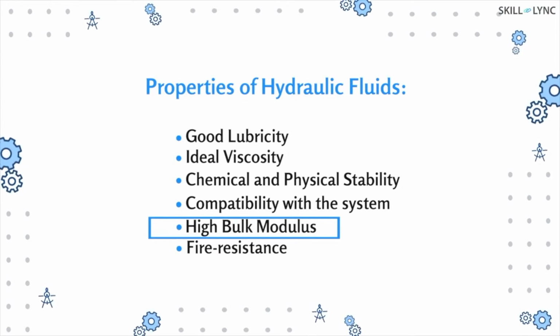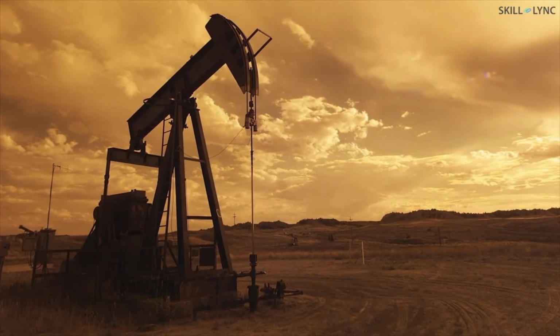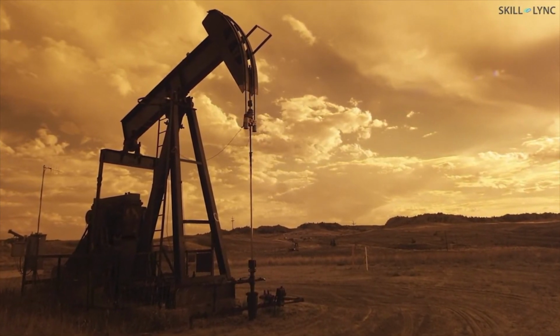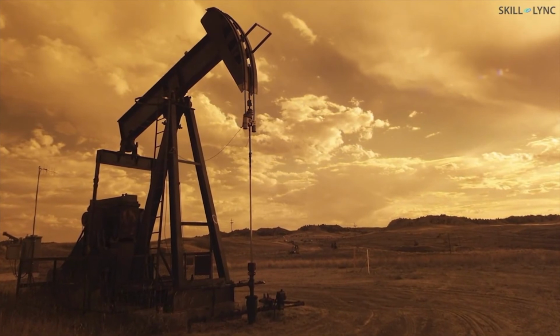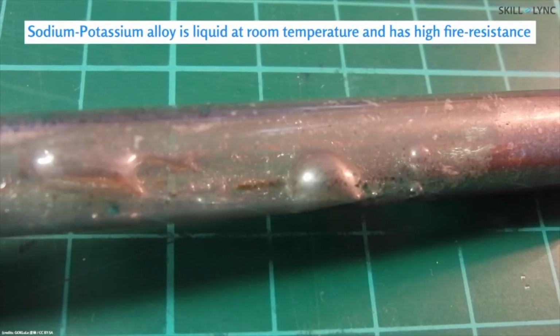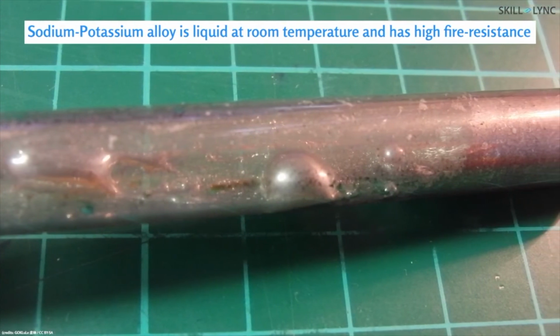Another property desired in a hydraulic fluid is fire resistance. Since most of the hydraulic oils used are petroleum derivatives, care should be taken while operating them. Otherwise, the fluid might ignite at high temperatures. To overcome this, synthetic hydraulic fluids having high fire resistance are used.